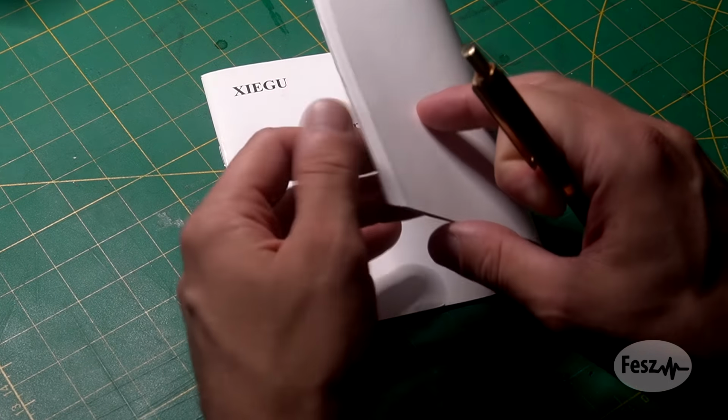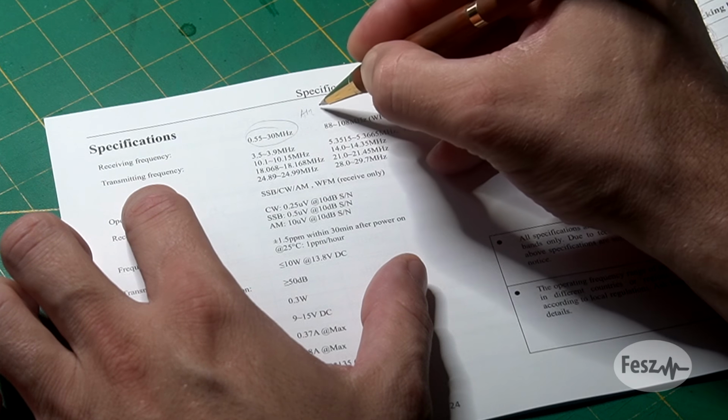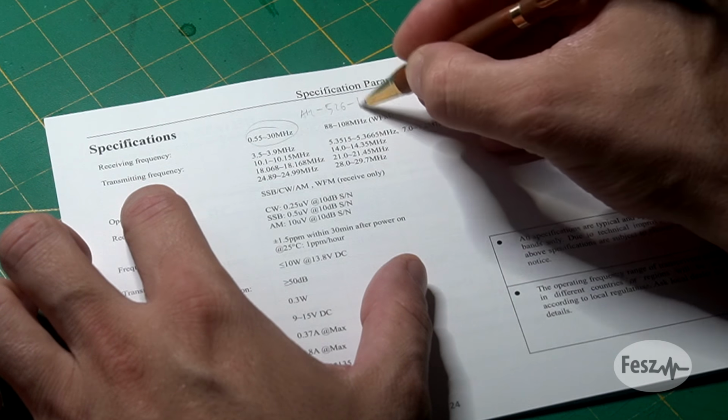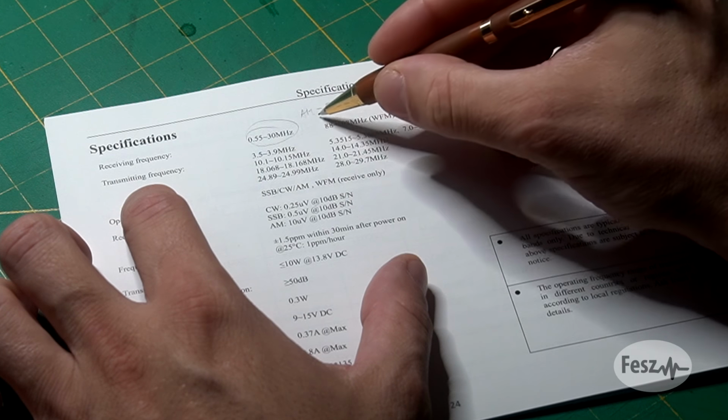After scouring the internet to see what other users of the same transceiver experienced, if anybody else was having similar issues, one thing stood out. The receiver has an input passband of 0.55 to 30 MHz. Therefore, certain users did report commercial broadcast overdriving the input and therefore leading to interference issues, mainly coming from the AM band. So the natural solution to this is to use a broadcast interference filter, commonly a high-pass filter.